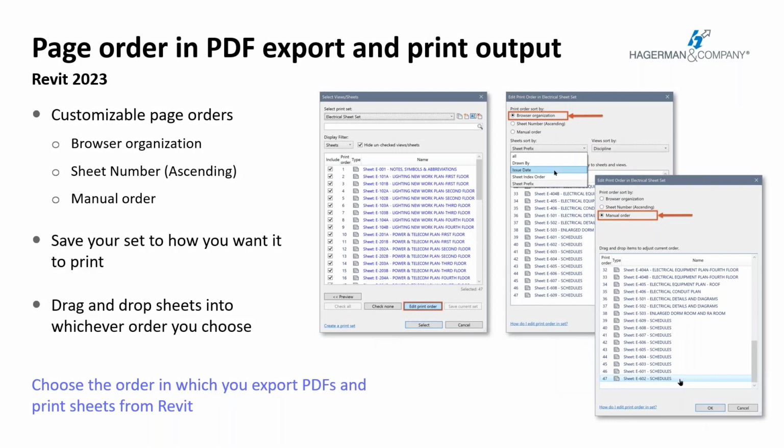All right, and this could possibly be the very best of the best as far as new features. Revit 23 offers the ability to choose which order you would like the page order to be for PDF export and print output. You can customize your page orders by predefined browser organization, ascending sheet numbers, or, and this is the key here, your own manual order, which is awesome. Manual order allows you to drag and drop sheets into whichever order you choose.